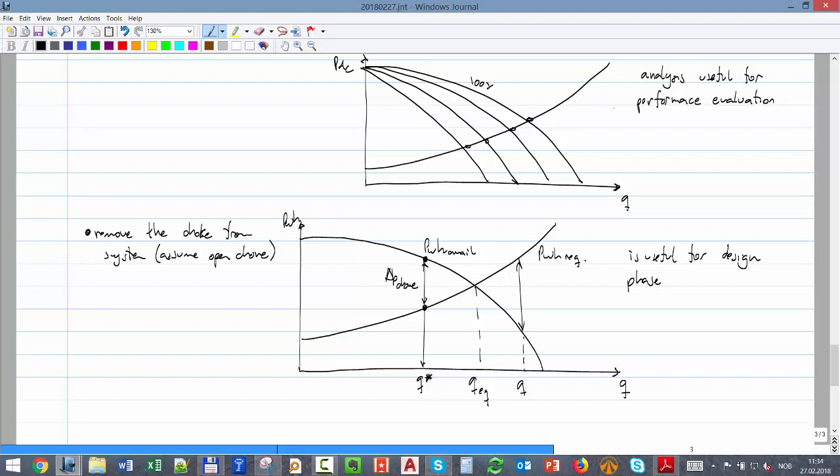Yeah, but remember, what is the tubing size going to make? The tubing size is going to change this curve. It's going to make it like that. But let's say it's like that, I still don't get there, and it's not something that I can regulate. So an option is to put a compressor, something that will take the available pressure up, bridge it, and bring it equal to the required pressure. So I need a compressor that will give me exactly this delta P for that rate. Okay?